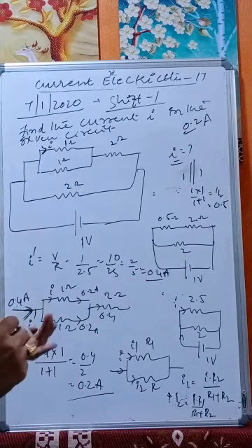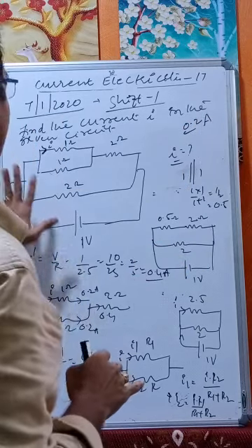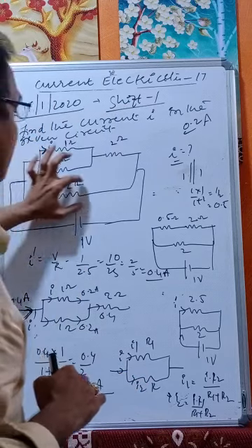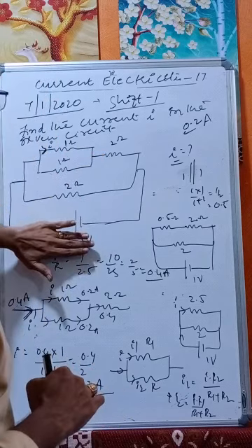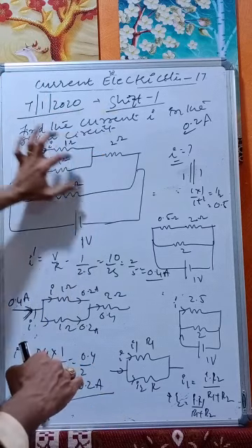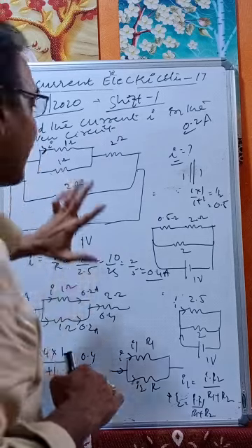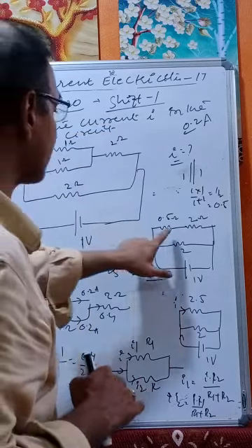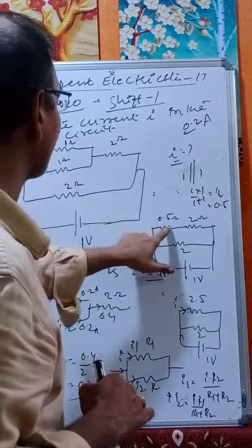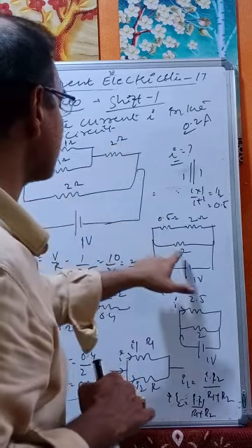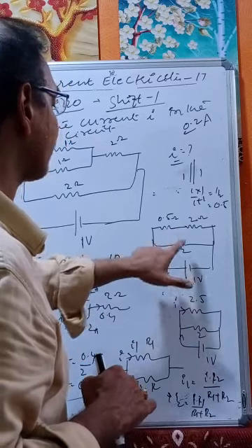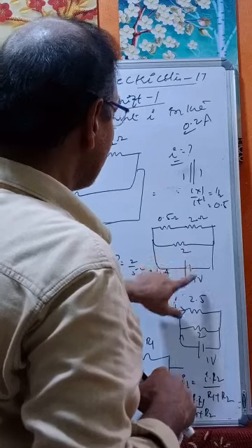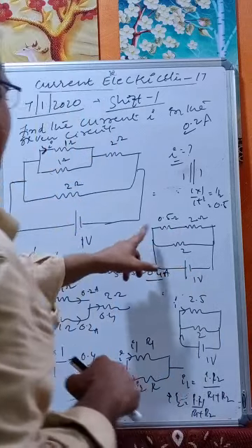So, what have we done? Nothing, very simple. Here we calculate the effective resistance of this branch. The effective resistance of this branch is 2. The same 1 volt appears across this branch and also this one because they are in parallel. Therefore, we have the voltage across this one. The current to that branch is, 1 parallel with 1 is 0.5, 2 is 2, and 2 is 2. Therefore, 1 volt appears across this one, and the effective resistance is 2.5.